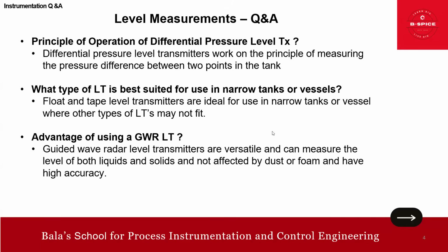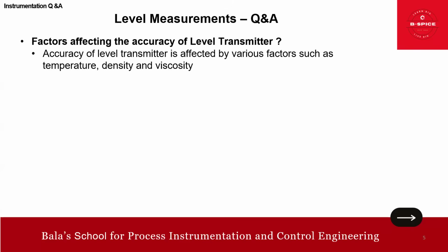And what is the advantage of using a guided wave? Yes, again, guided wave is versatile. It can measure level for both liquids and solids, is not affected by dust or foam, and has high accuracy. That is the advantage, right? Now, factors affecting the accuracy. What are all the factors? Various factors: the temperature, density, viscosity, all these factors affect the accuracy.